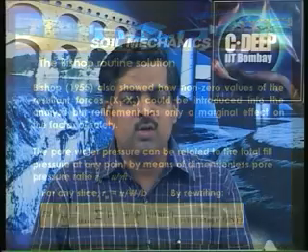If it is assumed that the slope is partially submerged, then a specific value for r_u can be given, or if the phreatic line is estimated within the dam or any slope cross section, then the phreatic line can be dictated. So, with that given condition, we can obtain the factor of safety of a given slope.